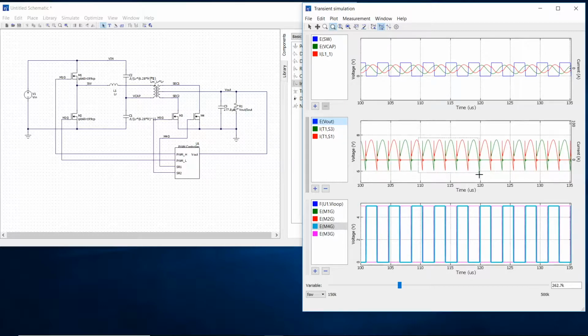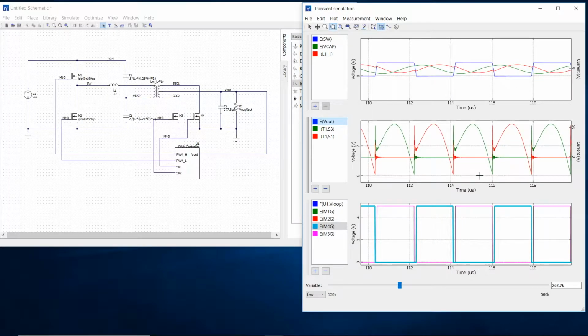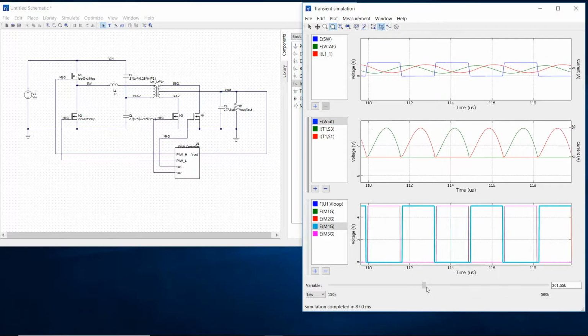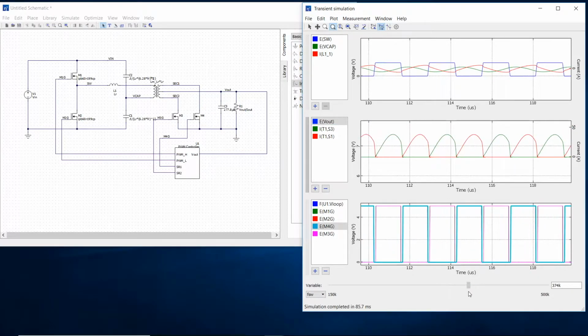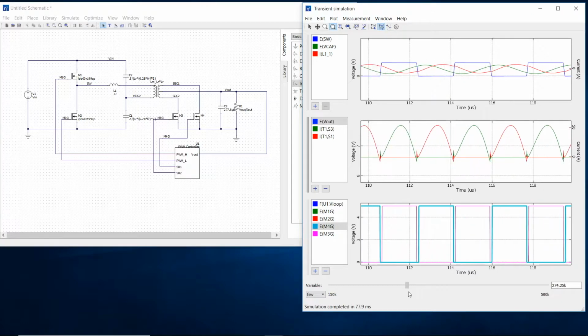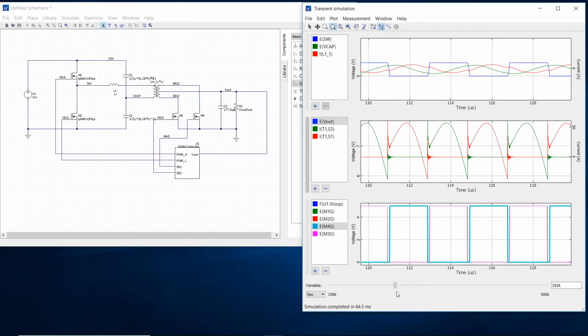At switching frequencies below resonance, the secondary side currents actually reverse and send energy back to the primary side. This will cause switching loss and additional circulating currents, so we want to avoid this. Let's look at how this effect shows up. At higher switching frequencies, the secondary waveforms look fine, but at longer periods, the reverse current starts to show up.